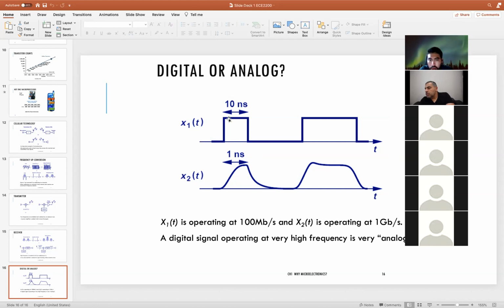When things were slow, ones and zeros look like this. When you put it on your oscilloscope, yeah, they look like square waves, zeros and ones. Let's say it's 0 and 3.3 volts, or 0 and 1 volt, etc. But as you get into multi-gigahertz digital signals, that's the signal frequencies in your cell phone, in your computer, microelectronics, at that level things don't look so binary anymore.